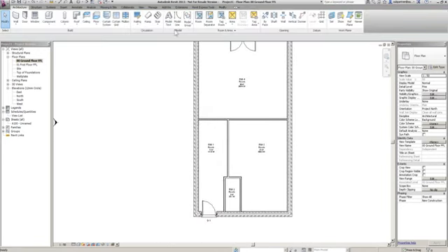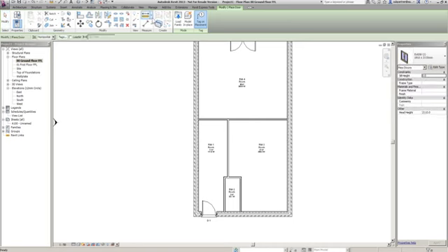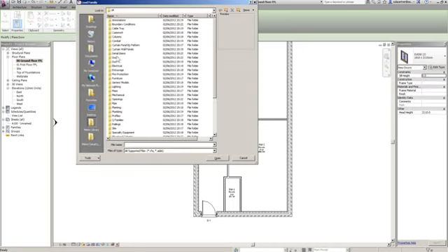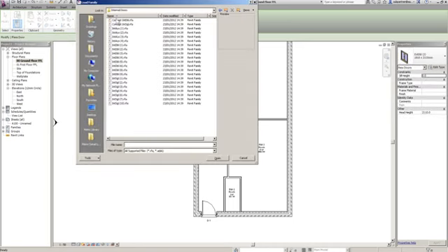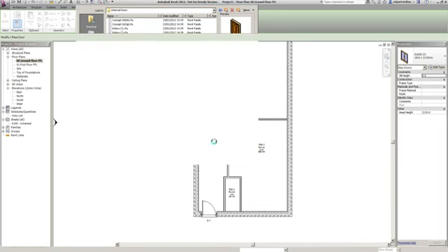Okay, I'm now going to put some internal doors in. So again, I'm going to load family. I'm going to go doors, this time internal doors, and just like I did with the external doors, I'm just going to scroll down so you can see the list of doors that comes with Revit. Everybody gets these. They come as part of the package, all inside your library. Okay, so I'm just going to load it in with a house. I'm going to just put in some 6-panel doors. That's fine. Open that. Give it a second. It will load them into the project.